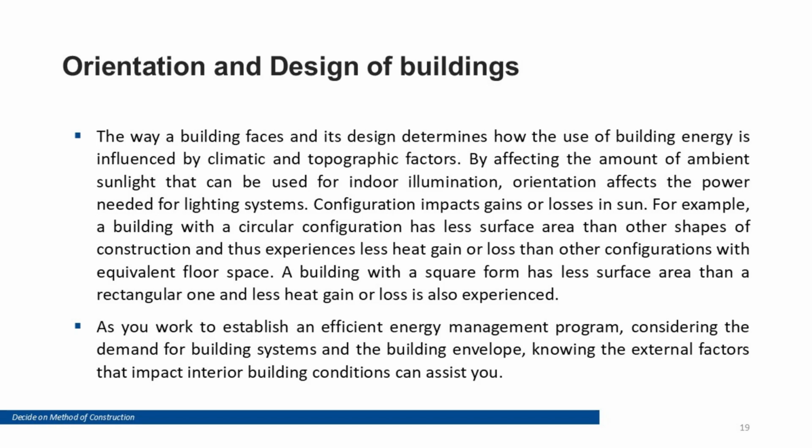Orientation and design of buildings. Orientation affects daylight and solar heat gain. Building form also matters. More compact shapes reduce surface area and reduce heat loss and gain. Practical controls include glazing placement, shading devices, and external surface colors. When the design supports the climate, construction can deliver performance with fewer band-aid solutions.